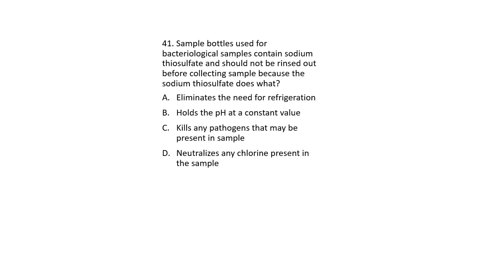Sample bottles used for bacteriological samples contain sodium thiosulfate and should not be rinsed out before collecting the sample because the sodium thiosulfate does what? Eliminates the need for refrigeration, holds the pH at a constant value, kills any pathogens that may be present in the sample, or neutralizes any chlorine present in the sample. The answer is going to be D. The sodium thiosulfate neutralizes the chlorine that's present in the sample, so that if there is bacteria, it will be able to grow. You don't want to continue to kill it, because you are, again, testing to see if your water is contaminated.